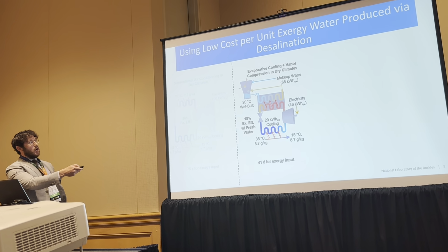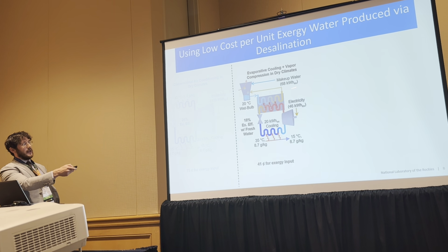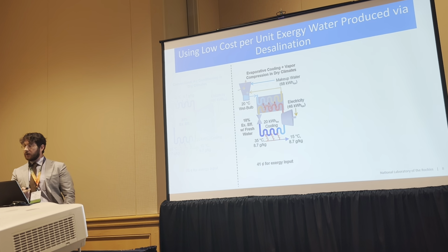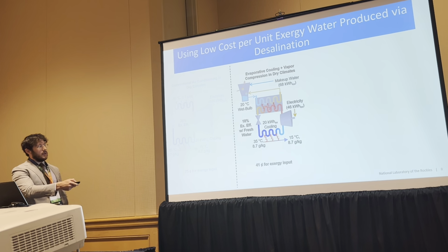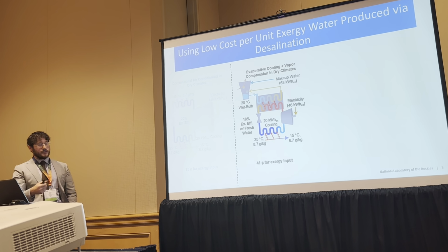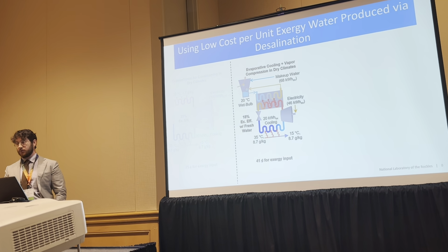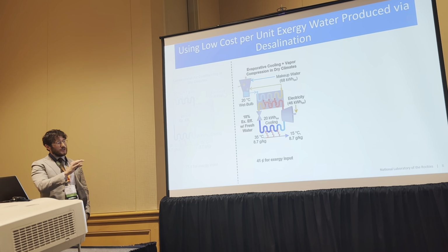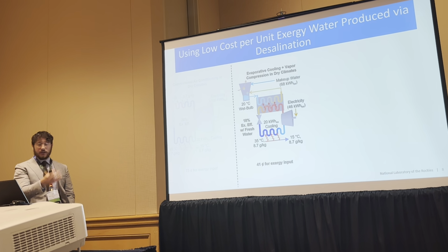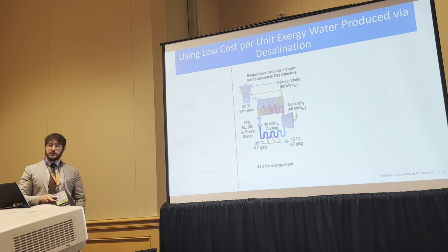And that's just because we've now switched some of our exergy input to this water in the evaporative cooler, and less of our exergy input is coming as electricity. And as I discussed on the previous slide, water is usually a cheaper exergy source than electricity. So even though the system's slightly less efficient, it's a lot cheaper to operate because we're using that cheaper exergy source.